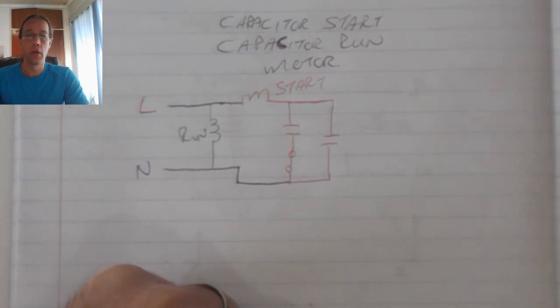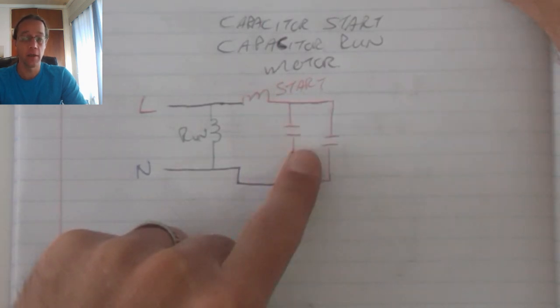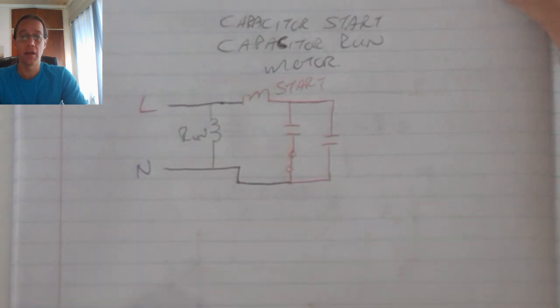Testing must occur on all motors before they can be connected to a supply to ensure that they are safe for use. These include the visual inspection, the electrical testing, which includes insulation resistance between the windings, continuity of the windings, and the earth test, as well as testing both capacitors. Ensure that the capacitors are discharged before testing, as well as checking any mechanical aspects: covers, nuts and bolts completely fastened, cooling fins, and so forth.